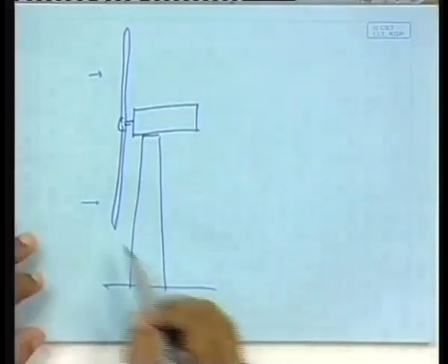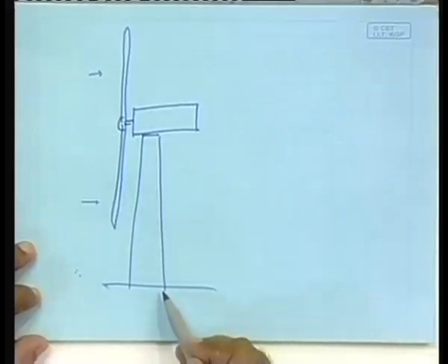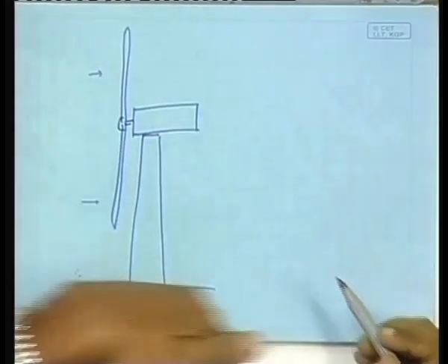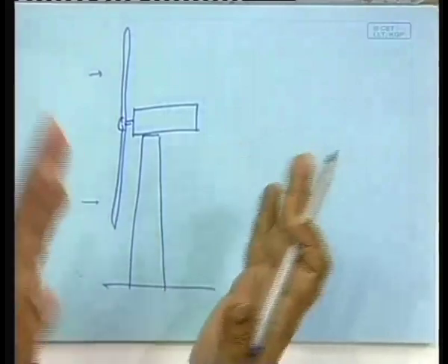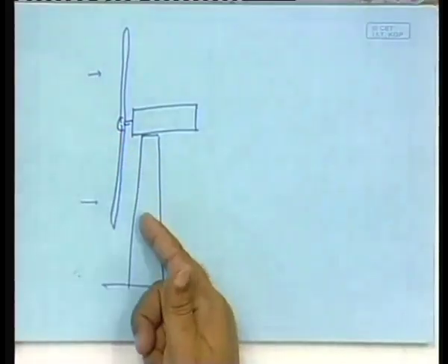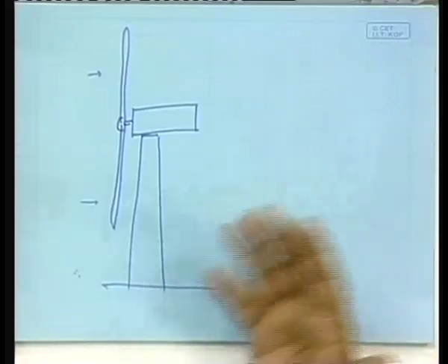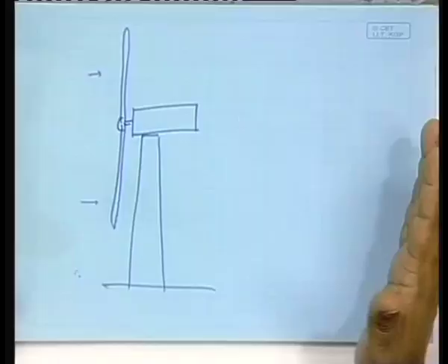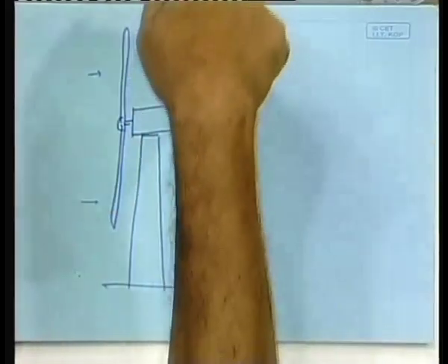But in both cases, where the tower stands, when the blade passes in front of that, just behind it there is a tower. So, in front of the tower there will be disturbed wind, that is something like the tower shadow. If the wind is coming from this side, you can easily see that it will be the tower shadow, right. So, in terms of wind, not in terms of light, wind will be obstructed by the tower, which will not reach the blade that is down there.